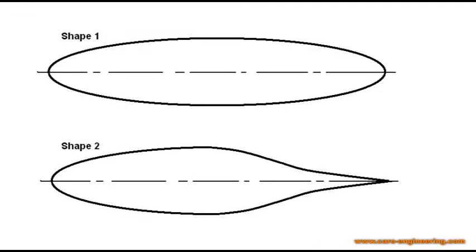The air is not just getting pushed out of the way, it also has viscosity, which means it sticks to the surface of the object. This causes another form of drag, the skin friction drag. This means that two objects that have the same cross-section but different surface areas can have different drag.